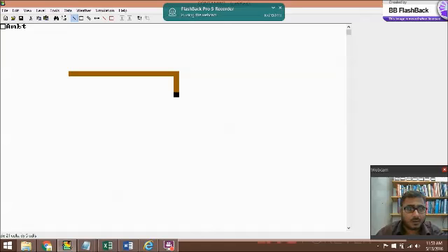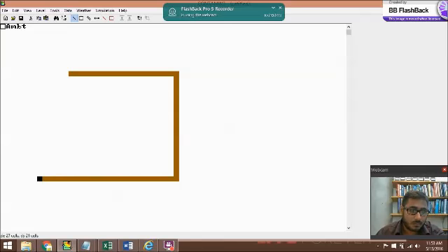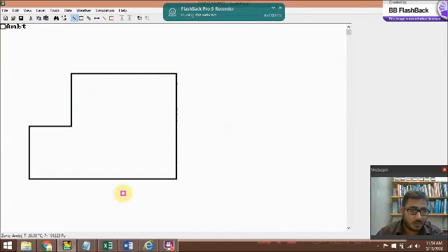While creating a wall, you cannot stop in between or click at the end of one direction. You just have to move your mouse based on what direction you want. So if I'm at the end of the wall, I just have to move in the direction I want and not click it. So maybe we have something like this. Yes, perfect. And when you are at the end of your junction, you just click it and your walls are created.